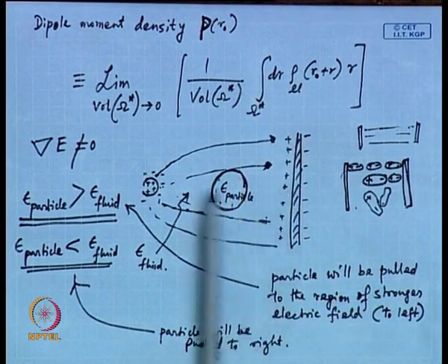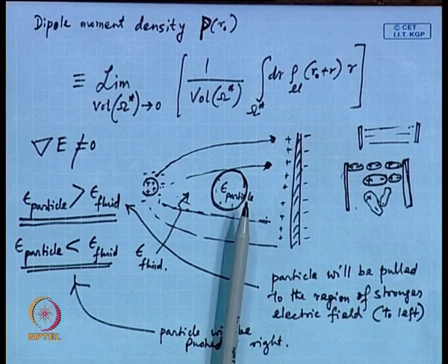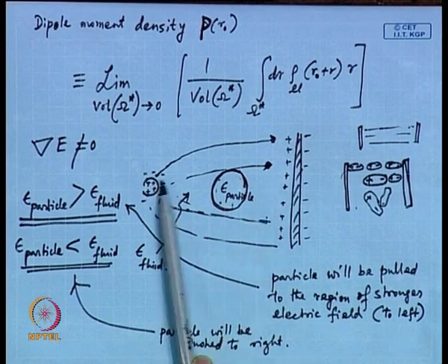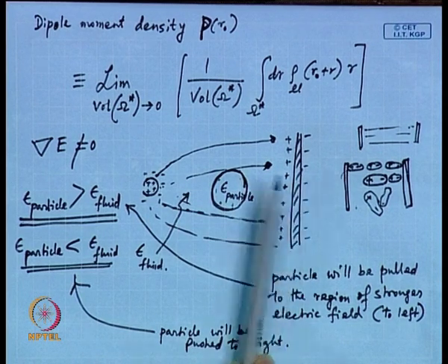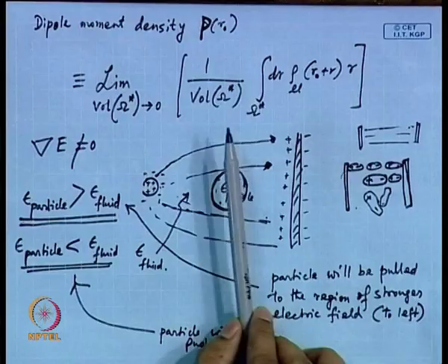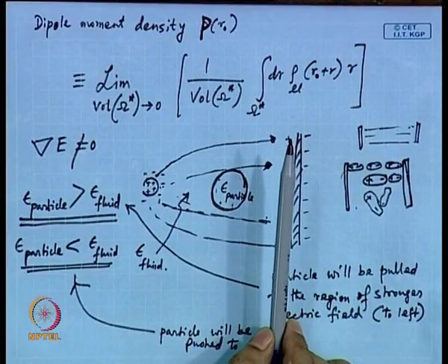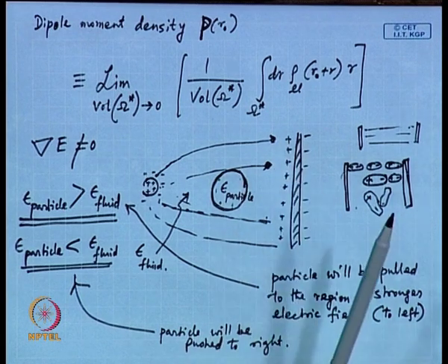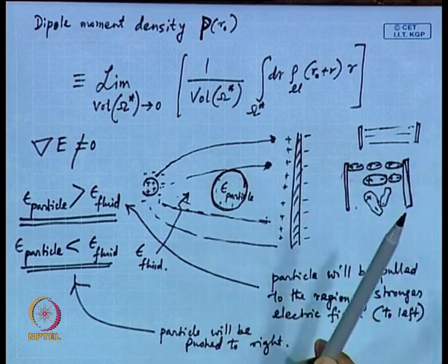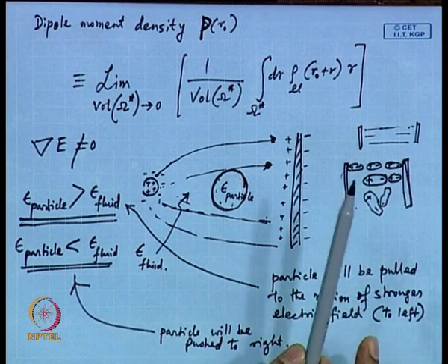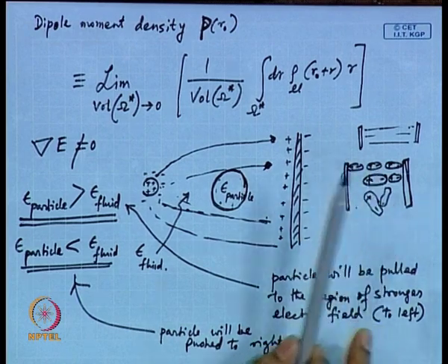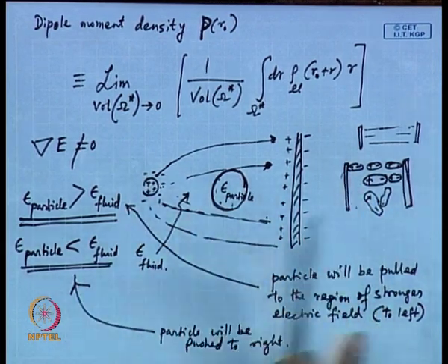Now, if you can align particles within this channel at various locations depending on their dielectric property, then when you receive them at the outlet, you can detect them, and against a pre-calibration you can find out for an unknown sample what particles you have. That is one way of doing it, using this DEP in a field flow fractionation mode, which researchers have already studied.